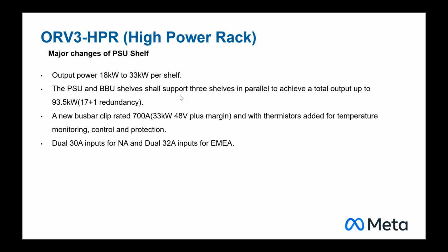So to achieve the rack level 93.5 kilowatts, first we need a solution for the bus bar. Of course, cooling is another problem, right? Rack level cooling. Liquid cooling is definitely needed. In the new data center, we already designed in the liquid cooling, but the capacity needs to be evaluated to support 93.5 kilowatts. But when I design the power supply, I don't want to design barely enough, right?